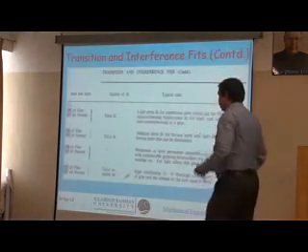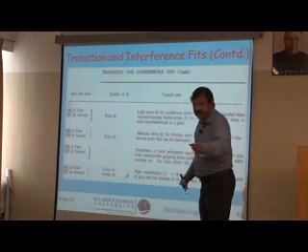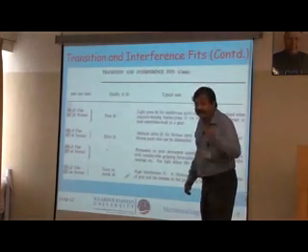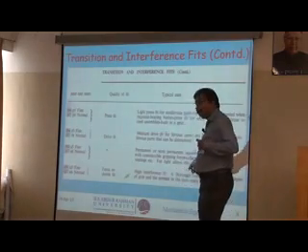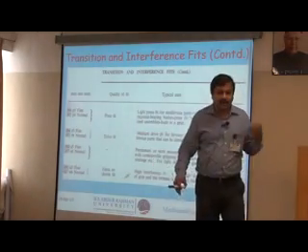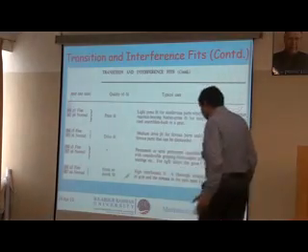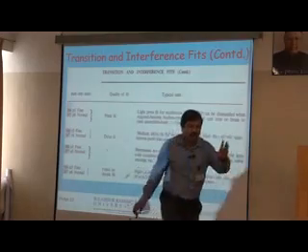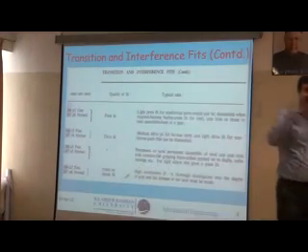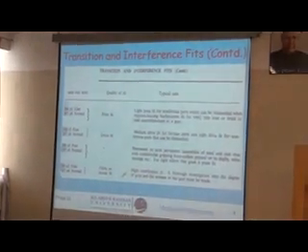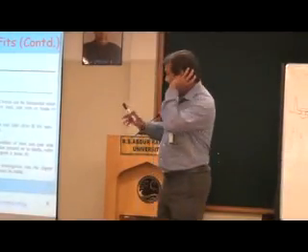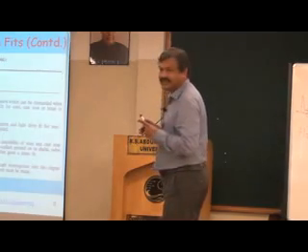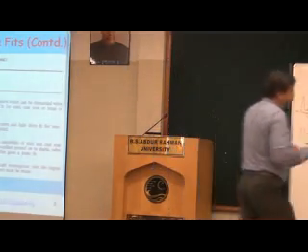So is it just press fit? Is it drive fit? Or is it heavy drive fit? Or force fit or interference fit? What shall I choose? I shall choose the second, drive fit. I don't want the force or shrink fit, because I cannot be heating and then shrinking. That is not possible for me. So I choose H7 S6.